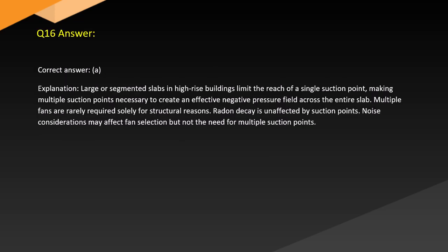Answer. Correct answer, A. Explanation. Larger or segmented slabs in high-rise buildings limit the reach of a single suction point, making multiple suction points necessary to create an effective negative pressure field across the entire slab. Multiple fans are rarely required solely for structural reasons. Radon decay is unaffected by suction points. Noise considerations may affect fan selection, but not the need for multiple suction points.